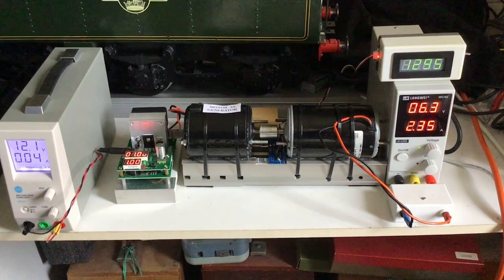What I've described so far is voltage control, where an increase in demand voltage results in an increase in speed. It's an inherently stable system, because if the train comes to an incline and the speed drops, Vg will drop and Vs minus Vg automatically demand more torque. The speed will drop, but only to a limited degree.